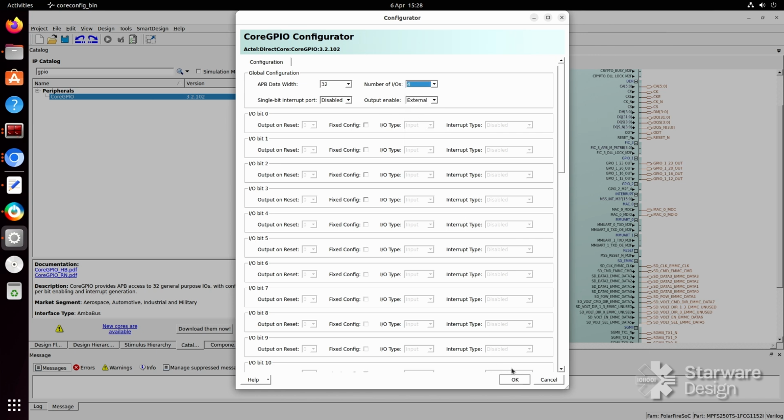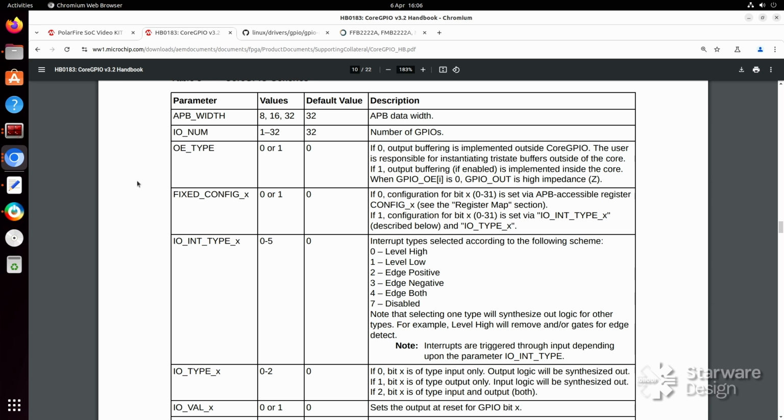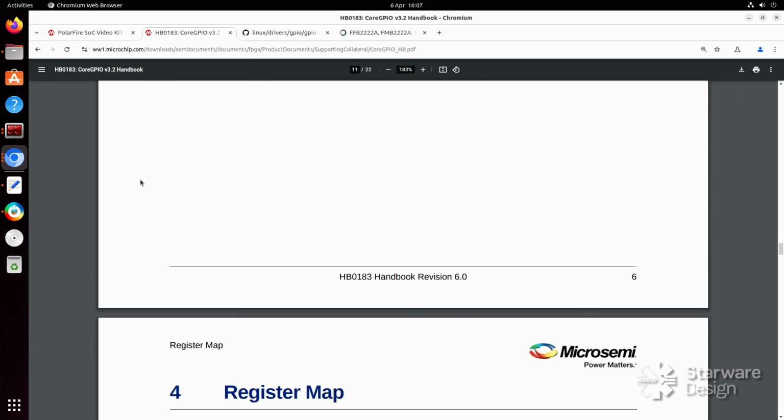Since we're going to use the GPIOs with the Linux device driver provided in the kernel, you have to configure the GPIO banks not to use a fixed function, input or output. While this would use fewer logic elements, you will not be able to use the GPIOs as input. When configuring the GPIOs as a fixed function, the configuration register is not present and will always read zeros.